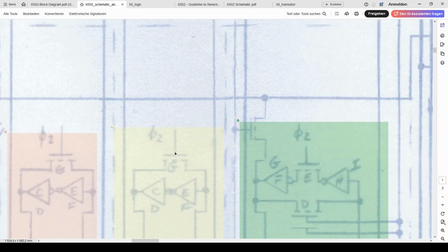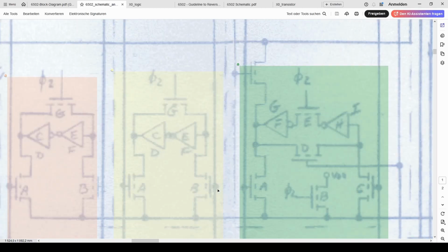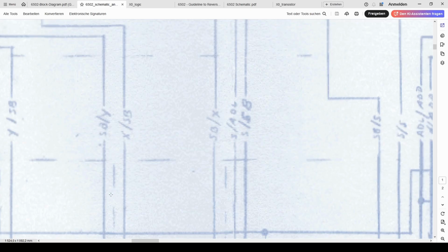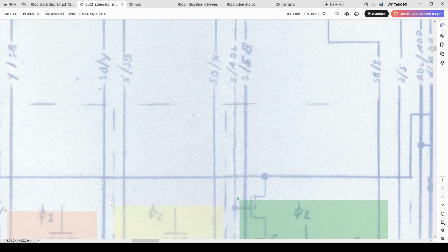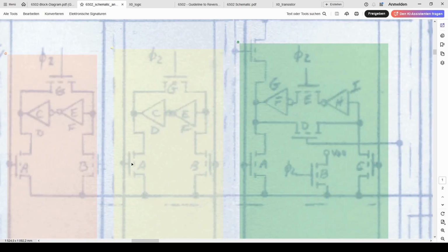And if we just follow those down, they eventually lead into these transistors. And so your deduction skills will probably lead you to deduce that if this line is X onto SB, and there's a transistor here which, as you know, will only let current pass through when the gate is powered, then this is probably the output onto what must be one of the special bus lines.